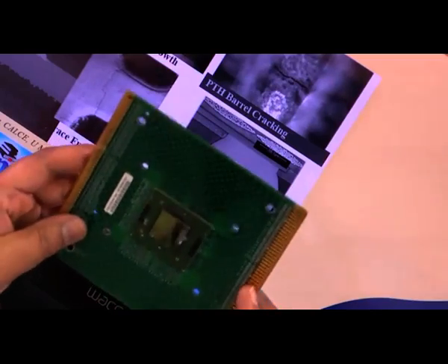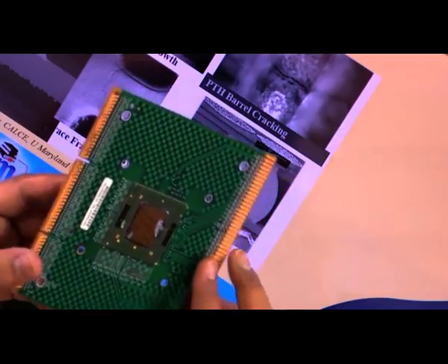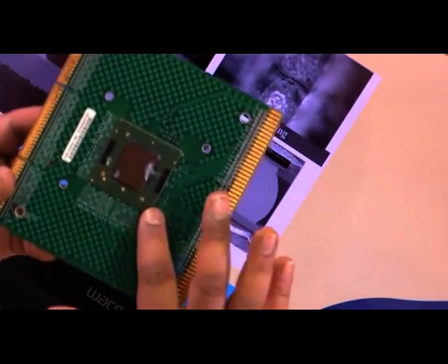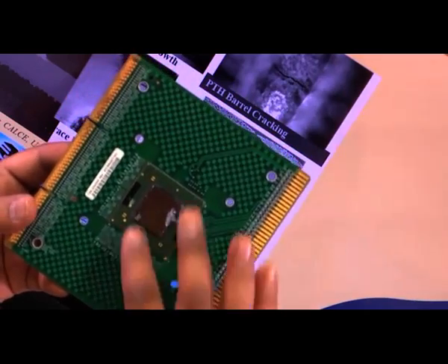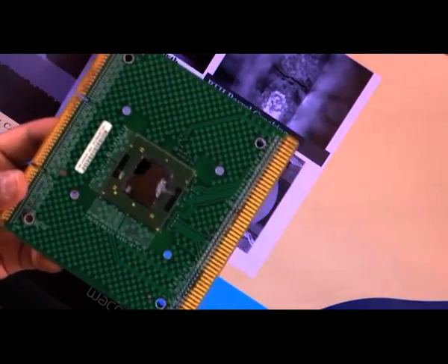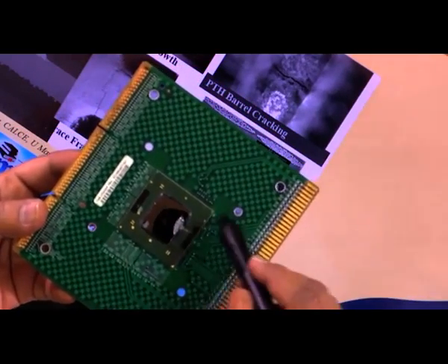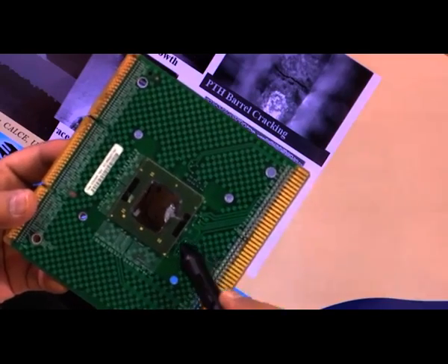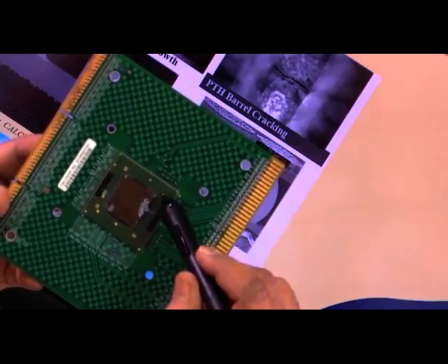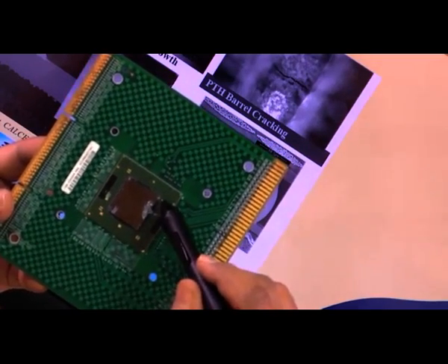Warpage is another big issue. Now, since I am showing this, let me also show you something very interesting. Say this is a ball grid array on an organic substrate or a package and on an FR4 motherboard. So, both are organic, the substrate is organic material, the motherboard is also an organic material. Okay. So, both organic, similar CTE. Now, this is a ball grid array attached, BGA attached between the motherboard and the package as well as between the silicon and the substrate.